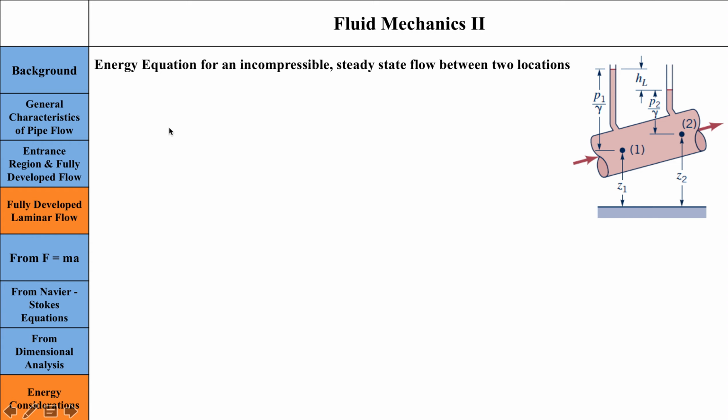And what that means is that we have a pressure difference to account for. We also have to account for the kinetic energy changes that may take place within our flow. Or we also have to account for the elevation changes that are taking place if the pipe is not horizontal anymore. And because of fluid friction, because of viscosity that we just talked about, we will also have an additional term here, which is the head loss term or the pressure loss term. Okay, so we have these four terms, and all of them should be equal to 0 in order for the conservation of energy to hold.